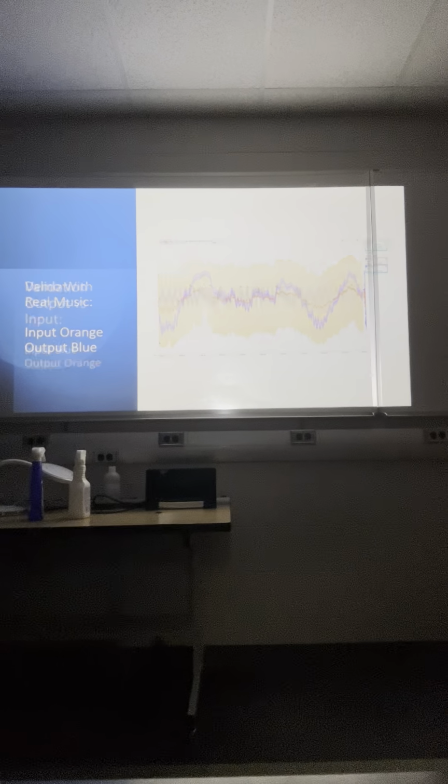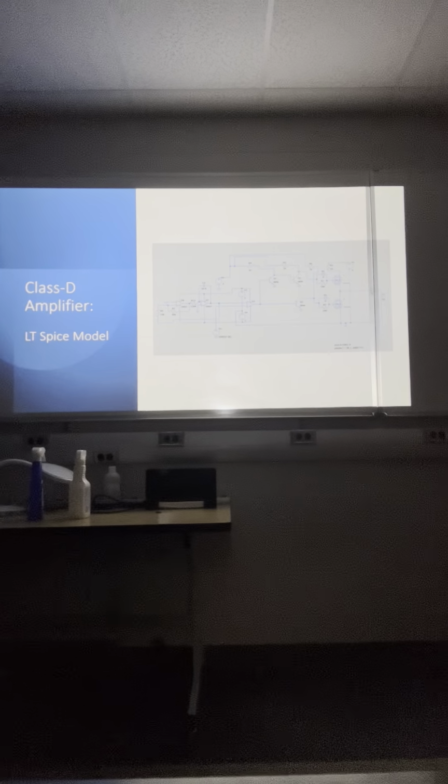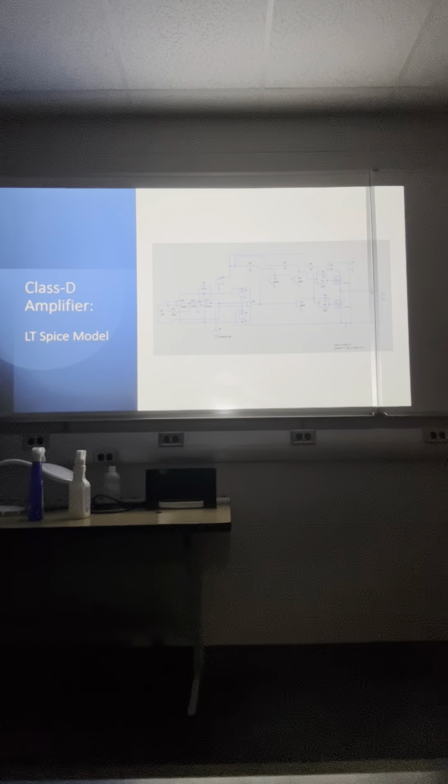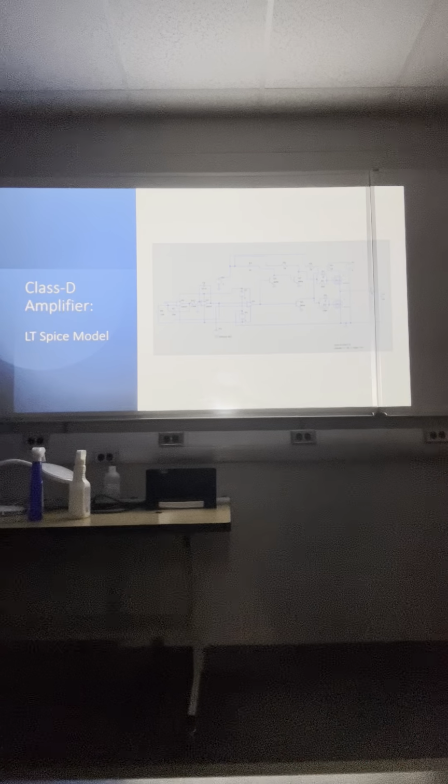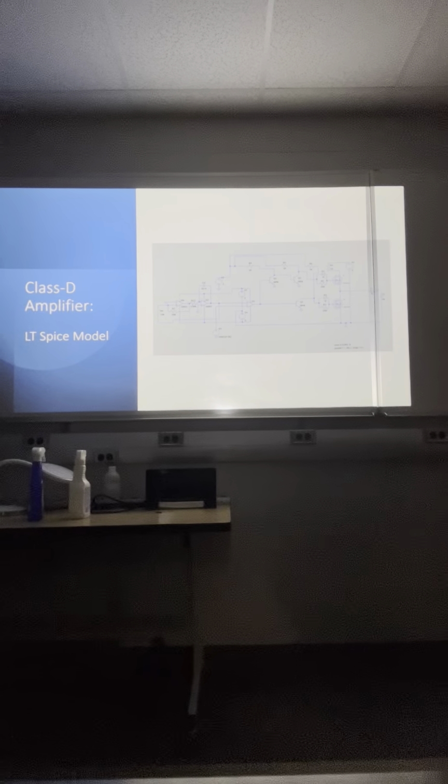So I guess before we go to the spectrogram, one interesting part about the whole design, and Danny definitely touched on it, is that one of the biggest issues while designing this Class D was RC charging. It was a huge issue, right? All these active components, like these MOSFETs or BJTs, all have this gate capacitance, and we found that whatever the component may be, it will not fully turn on even if it passes the threshold level, whether that be the gate-source threshold level or whatever current threshold level it needs at the base. It won't turn on fully or as fast unless the entire gate capacitance is fully charged.